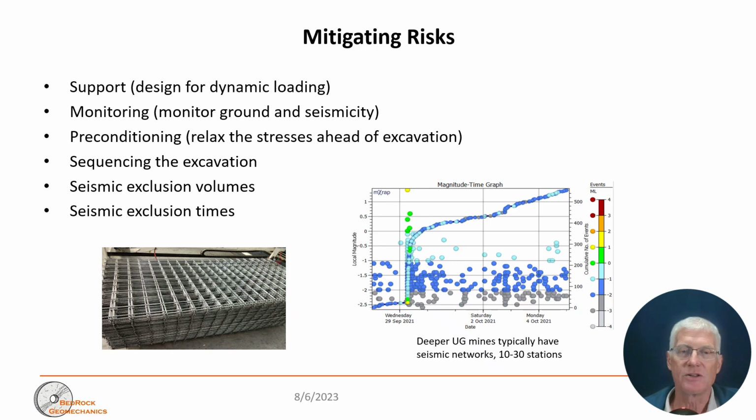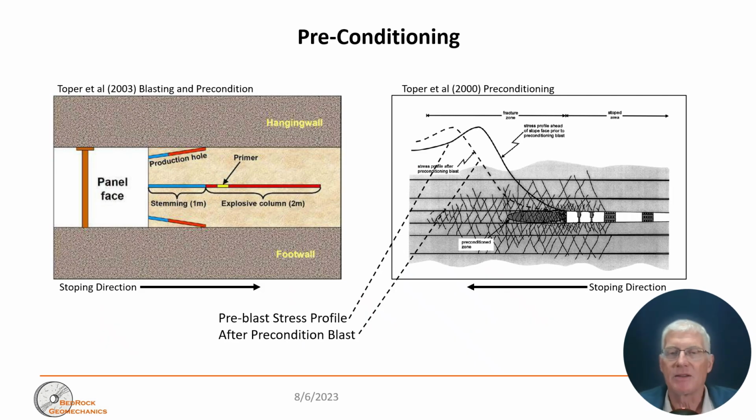The next thing you can do to mitigate the dangers is what's known as preconditioning. Two diagrams there. As you're doing your excavations, you drill out quite a way in front of where you're planning to go, lay a charge out there, and then blast to cause fractures. The fractures slip slightly and relax some of the stress in the area where you're going to be mining. So as you mine into the area with the actual excavation, you've relaxed some of the stress. That's the idea behind preconditioning.